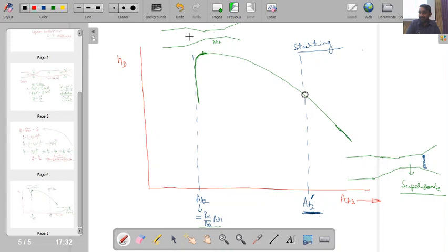Okay, so considering the economics and complications of this area, for the majority of applications, diffusers are operated at certain conditions other than the highest efficiency conditions. If it is not operating at highest efficiency, then the pressure ratio between exit and inlet will be large, and you have to supply more pumping power, so it gives slightly higher operational cost. However, you will be able to achieve the desired operation.